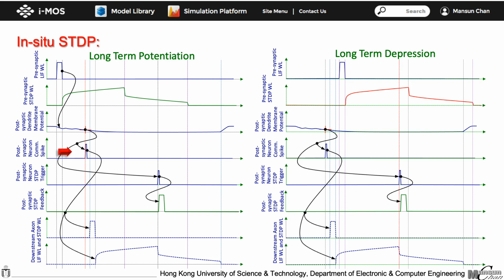When the neuron fires, the signal is passed to the next neuron immediately. And after some delay, a pulse is generated as feedback to the current synapse. As it is in the low voltage zone of the STDP waveform, M1 is only partially turned on. Therefore, only a low voltage appears across the PCM memory to set its resistance.